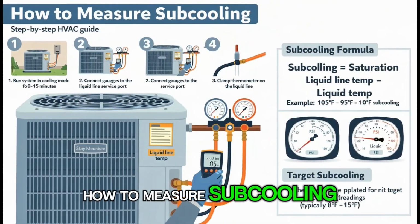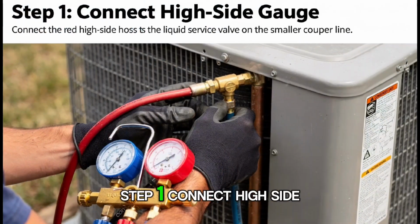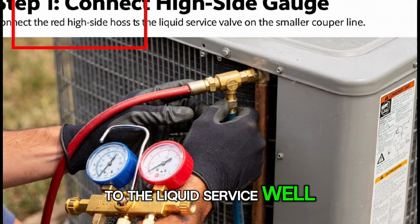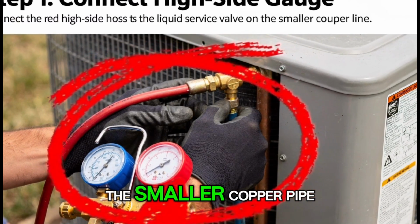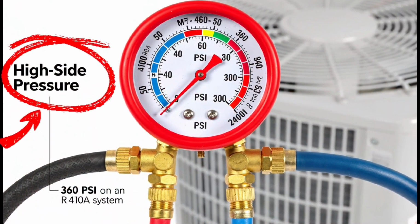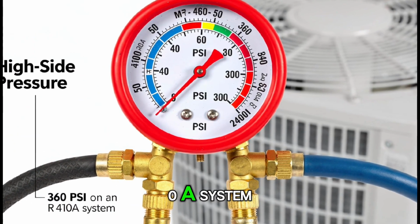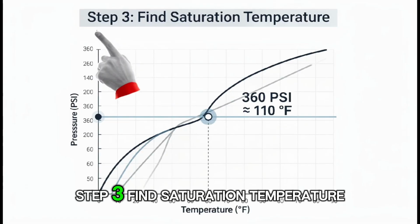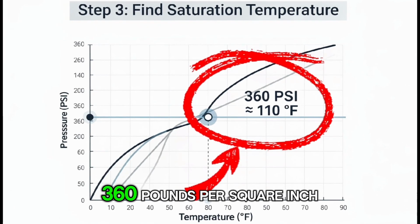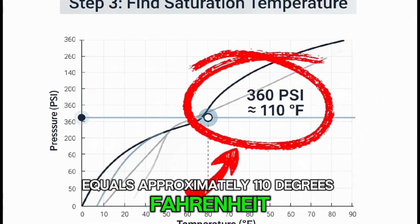How to measure subcooling? Let's calculate subcooling step by step. Step 1. Connect high-side gauge. Connect your gauge to the liquid service valve. This is usually connected to the smaller copper pipe. Step 2. Read high-side pressure. Suppose the pressure is 360 pounds per square inch on an R410A system. Step 3. Find saturation temperature. According to the PT chart, 360 pounds per square inch equals approximately 110 degrees Fahrenheit.